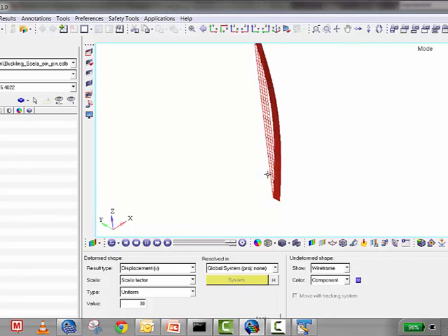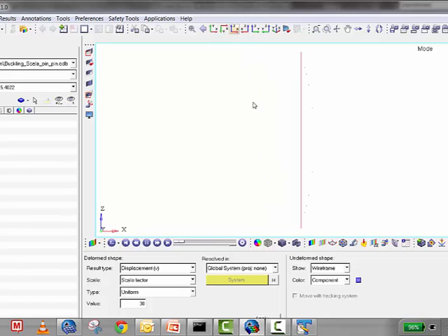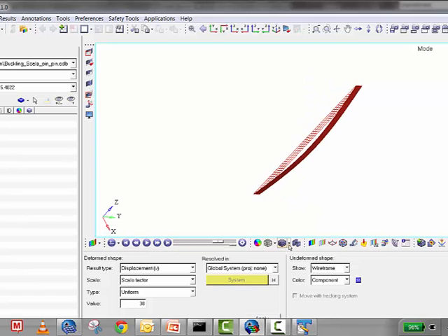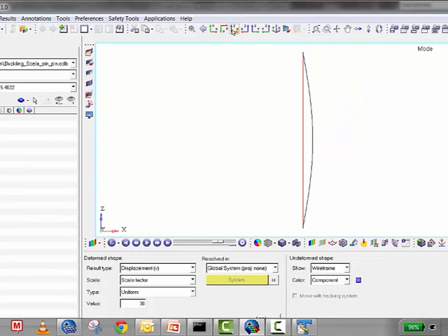That's it. If I have to see it in a proper side view, I'll just give some scale factor so you can easily watch the deformation. So this is the pin condition deformation, and the eigenvalue we got is 5.4022 for our corresponding load of -4 Newton.